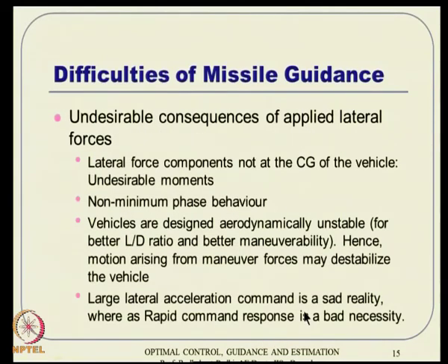There are several undesirable consequences also. Everything does not happen as nicely as we would like to see. First of all, lateral force components are not happening at the CG, so obviously there are undesirable moments, and largely they also result in non-minimum phase behavior, especially when you have a tail control vehicle. Okay. And then the vehicles are also designed aerodynamically unstable.